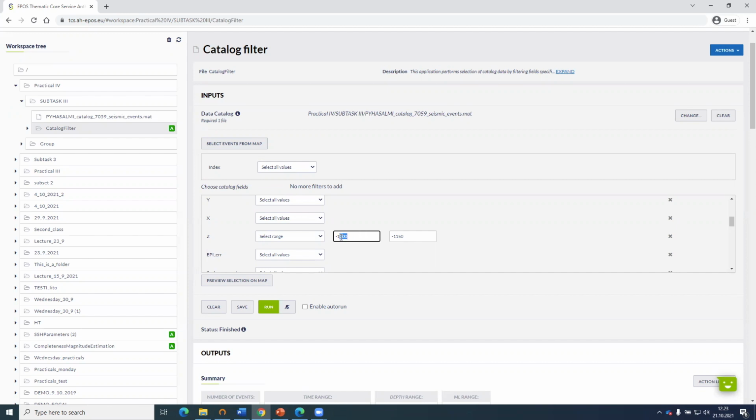So I think that the bottom was somewhere something like that, and since we determined that most probably the highest point of the ore body, the top part, would be somewhere at 1000 meters, that's 500 meters in the vertical direction, the dimension of the ore body. So we just need to divide this into 3 parts. I think we could put that the lowest part would contain everything from minus 1500 meters to minus 1350 meters, so 150 meters. And we just run it.